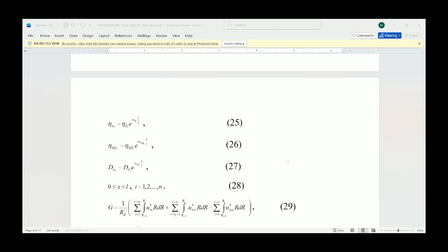In this equation, N1 is the number of layers in the internal arm of the crack. U0I asterisk, U0VI asterisk, and U0UI asterisk are the specific complementary strain energies in the cross sections of the layers in the internal and external arms of the crack behind the crack front, and in the cross sections of the rod layers ahead of the crack front.